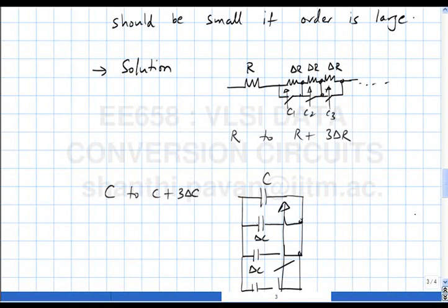By the way the IC is made, all resistors and all capacitors will be off by the same factor. So once I measure one resistor and one capacitor, I know how far my RC time constant is from the required value, and I can set the right code.